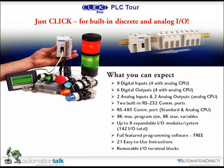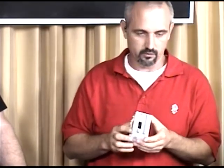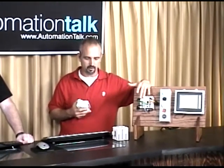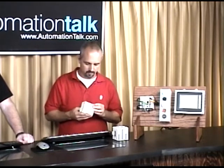Well, first of all, the CLICK PLC is built for discrete, and then we added analog. And as you can see, I'll just try to demo some of these in my hands. You can actually buy one of these modules, which is the processor. It has some built-in I/O on it, and you can get away with just using one of these. Now, you have to power it from some other source, so you can purchase a power supply like we've got on this other one over here. Got a couple little demo units here. You can purchase an AC or DC power supply there, but you can also supply it with an external power supply. And as you can see, you got digital in, digital out.